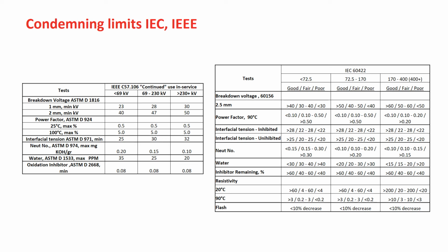Water contamination happens because of the condensation. A low water content is necessary to achieve adequate electrical strength and low dielectric loss to maximize the insulation system life and to minimize metal corrosion. Usually the water content for the oil delivered in drums is less than 30 ppm. Most of the power distribution companies have installation for oil dehydration. In that case, they can remove the water from the oil before filling the transformers.